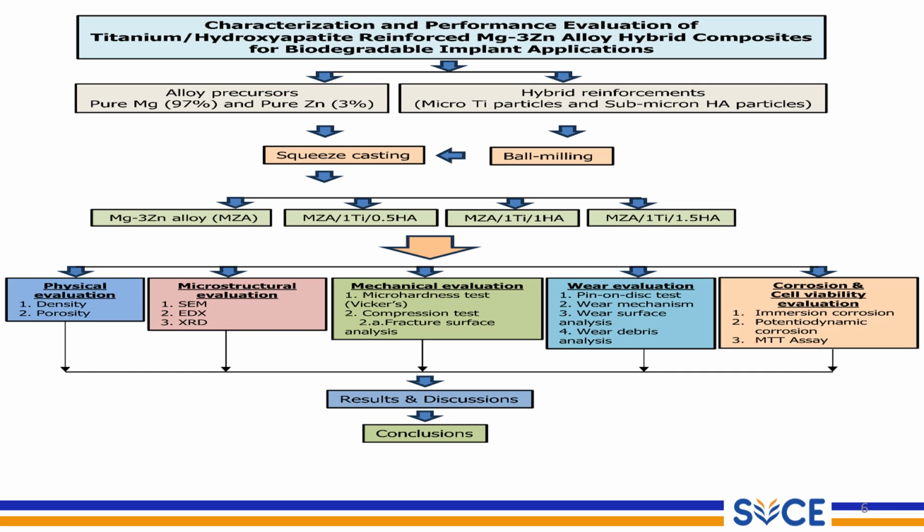These tests we need to carry out in 2 different laboratories. One is from the mechanical side, another one from the biology side. Biology means the biotechnology side. On the mechanical side, we have 3 major areas. One is the metallurgy side: XRD, SEM, EDAX. Another one is mechanical testing: compression, tension. Then the important ones are hardness and wear. These are all mechanical testing. Then the major elementary thing here is density and porosity.